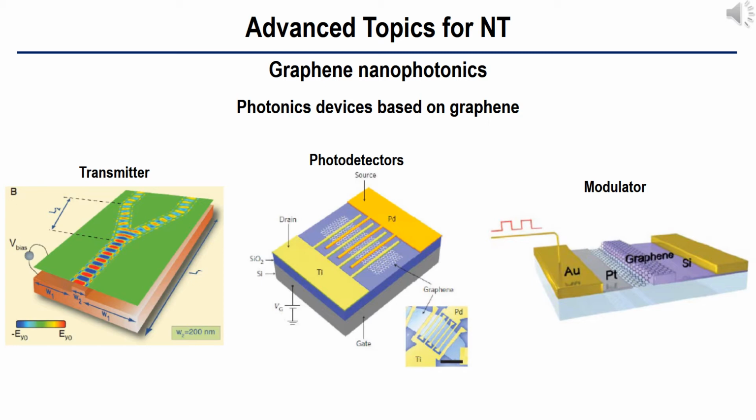Typically, in this spectrum, we need metallic fingers due to limited current generation, as shown in the left, middle, and right figures. For example, for graphene-based photodetectors, error-free detection in the optical carrier frequencies has been demonstrated with a 10 gigabit per second link at the telecommunication wavelength of 1550 nanometers.